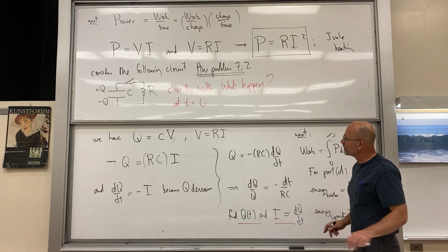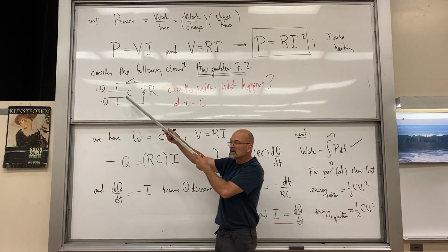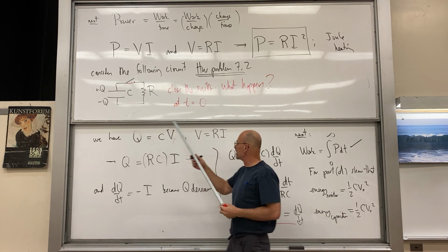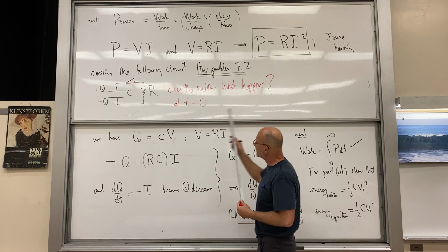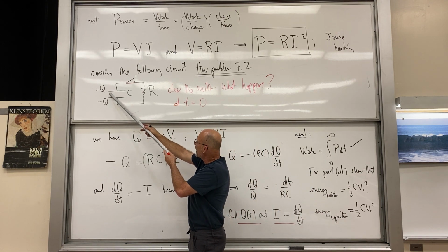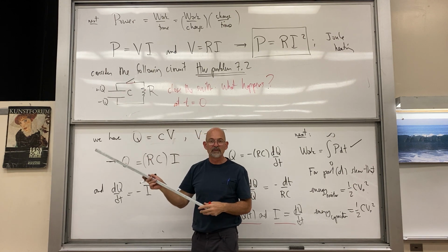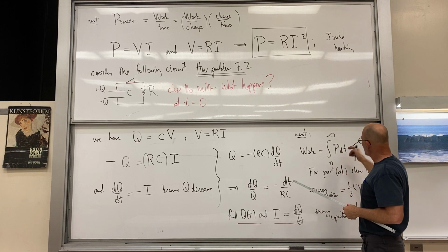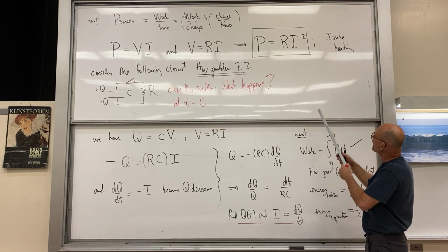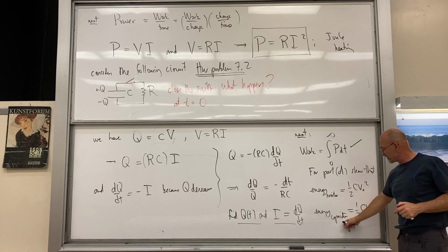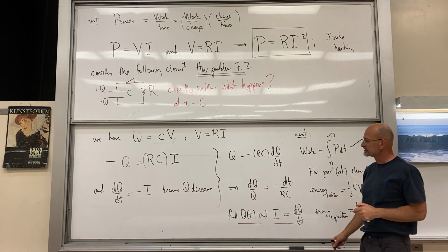Right, the energy in the capacitor is stored there once the thing is running. And actually, as time runs out, the current stops flowing, and you've got the same voltage drop across the capacitor that you have across the battery. Okay. So using this type of calculation, 1/2 of the energy is burned in the resistor, 1/2 stored in the capacitor.